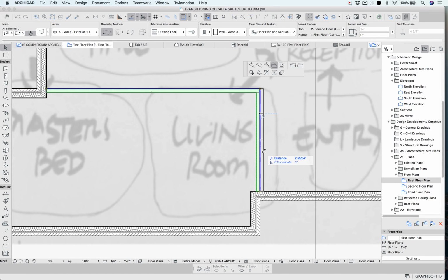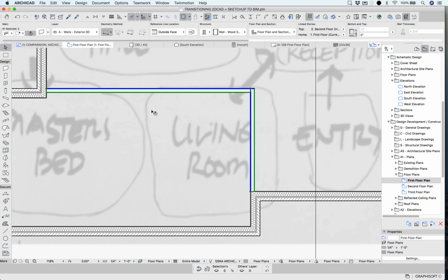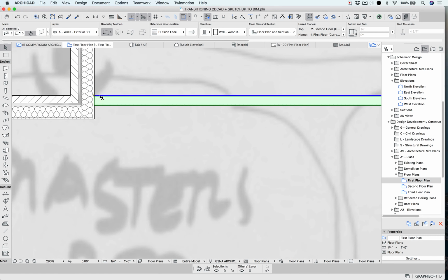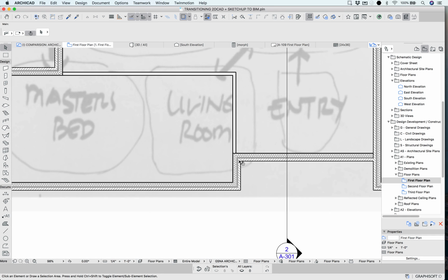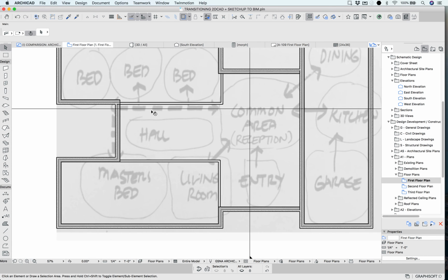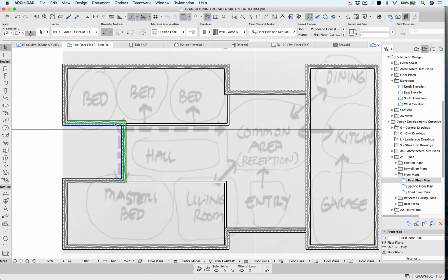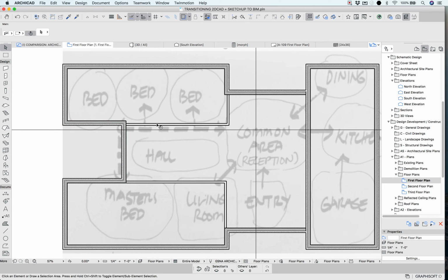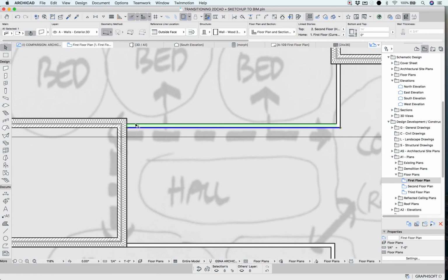If I wanted to change where this wall actually lives, first off, we have this thing called a reference line. You could flip it if you want to, if you're looking for a different approach with this, but you can also begin to offset my edges. I can begin to offset my edges in order to match my drawing as necessary, right? So just wanted to show you there are many different ways that people get started and start to develop this model. Once again, I've kind of used what was there.